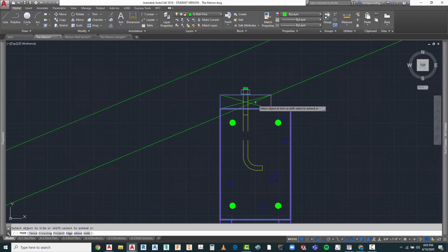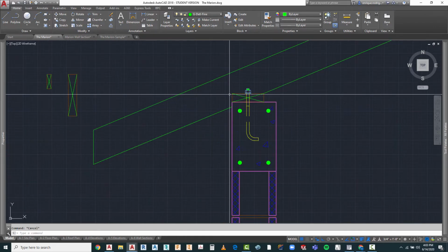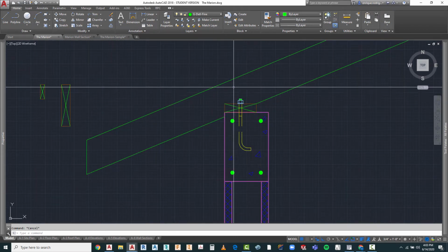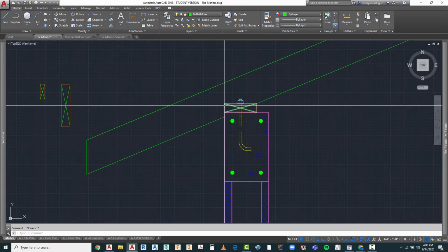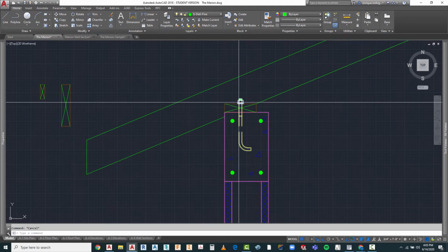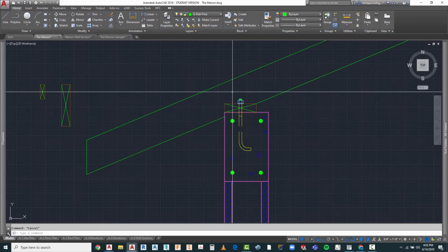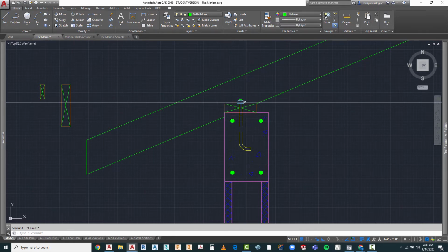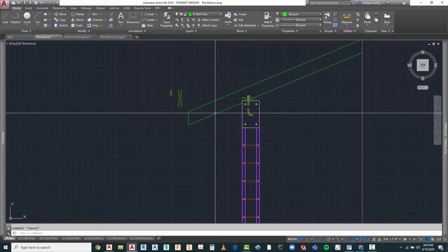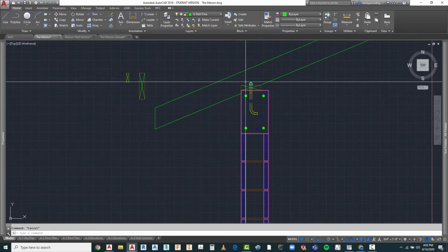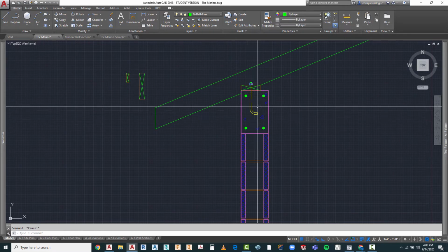And trim it with that. And I'm going to remove this and remove this. And that cut is what's called a bird's mouth cut. So what it does is allow this rafter, rather than resting on a corner, to have a bearing length right here so that the corner of that rafter would not be crushed, plus it gives it more capacity in terms of the ability to bear on there. So there is our rafter. There's our top plates, top of tie beams, etc.